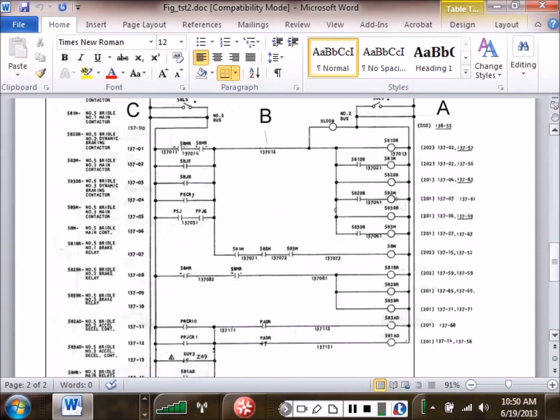And normally what we do is we have a crimp-on terminal that comes around all four sides, and we crimp it down on the stranded wire, and then I terminate it with a terminal, right? You understand? And then what they do for those terminals is that's where the wire number will be, right at the terminal. So you can't find wires getting to it, but you can find wires when they get there, right? Does that make sense?